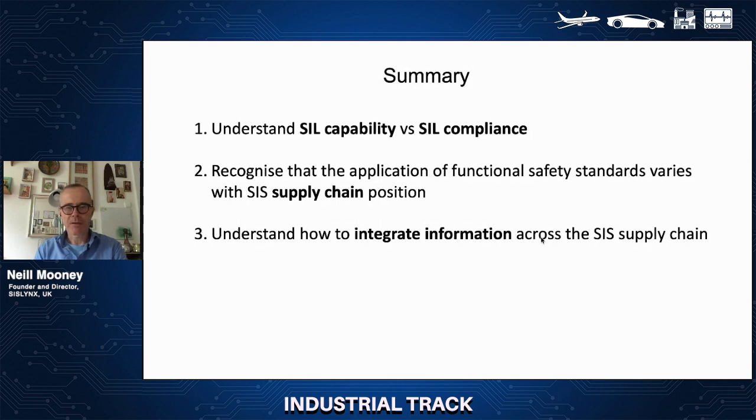So if you followed your workflows, you have managed your systematic capability, then you can say, well, okay, we're SIL capable, but you're not compliant until you are actually at the end user location and the SIS is installed and operational. And the reason for that is because the compliance part of it requires a risk assessment, which can only actually be undertaken at the end user location once you understand all of the different aspects of that context.